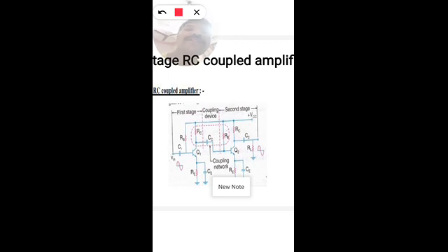But with the temperature dependency of the transistor, the collector current increases because the reverse saturation current doubles for every 10 degrees centigrade rise in temperature. So the collector current increases with temperature. This shifts the operating point up on the DC load line in the upward direction towards saturation, so this increase in the collector current has to be brought back by decreasing it by the same value.